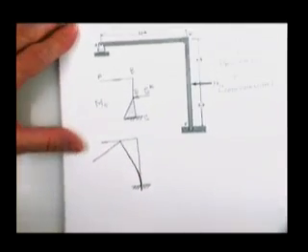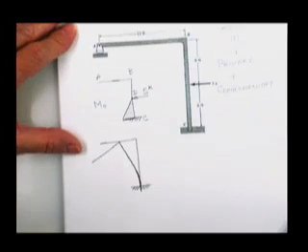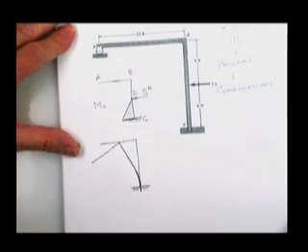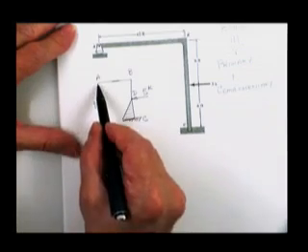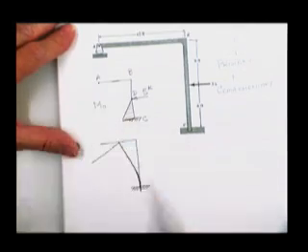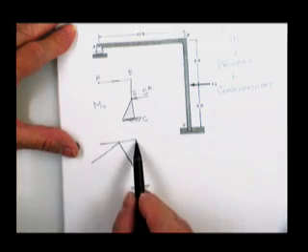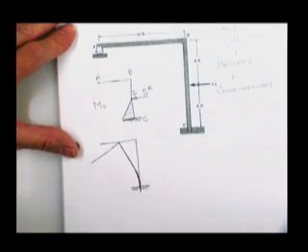And when you say, why didn't point B move down a little bit? Because I have exaggerated these deflections probably about 1 times 10 to the 6th. When I show you the deflected structure, this point really moves to the left 1/4 of an inch. And does this point here move down slightly? Not that I can see.